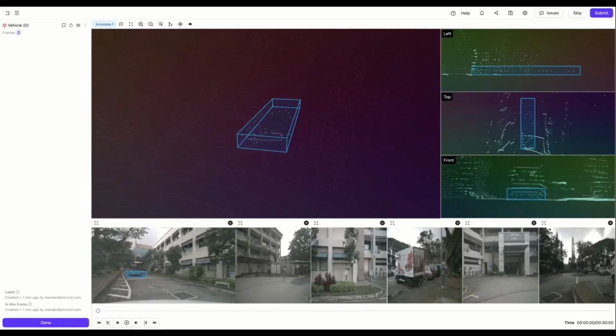And this is really helpful to see. It helps make me very aware of where this cuboid is in space. And it also makes it really easy to see which parts of the object that I'm trying to annotate I've missed. The other cool thing about this view is depending on the pane that I'm looking at. So let's focus on the front pane right now. This view actually highlights the points in the cloud itself that I may want to add to this annotation. So you can see that the points at the top half of this bus, they're not annotated, but they are highlighted. And so that indicates to me that those points exist in this plane, and it just makes it really easy to see where the rest of this bus is if I'm looking at it from the front.